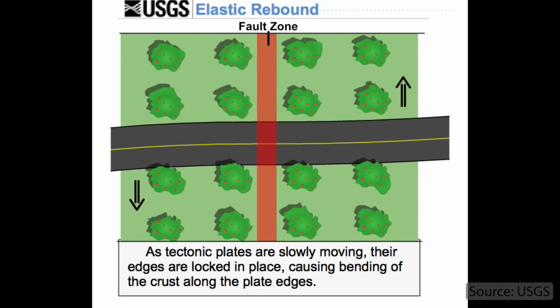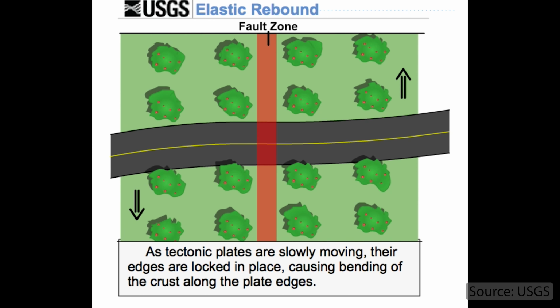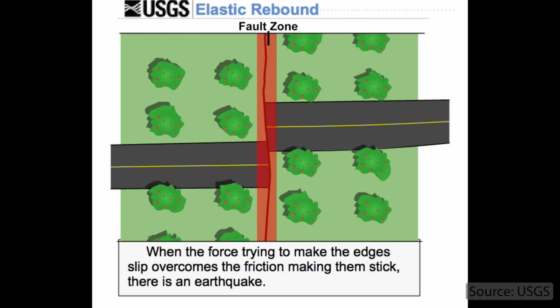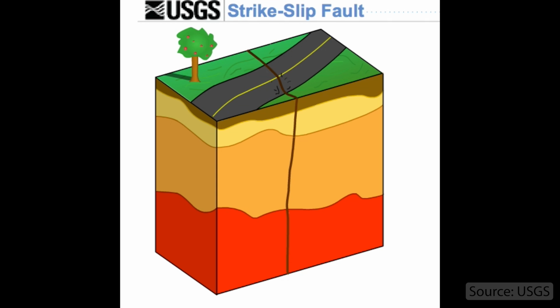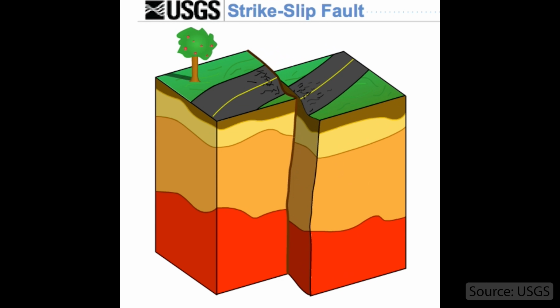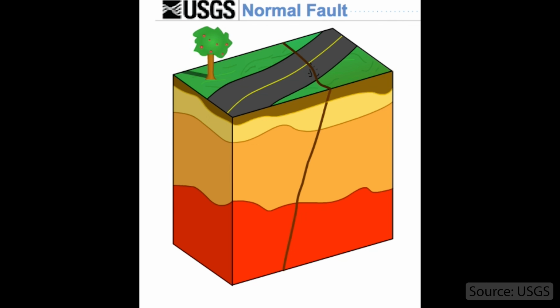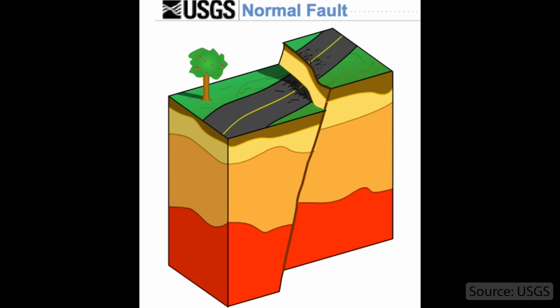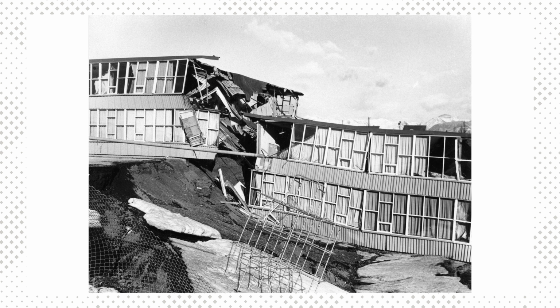A strike-slip fault manifests by predominantly horizontal displacement, as plates slide parallel to each other. This can cause roads to suddenly be misaligned, in addition to generating strong ground motion. In contrast, a normal fault is characterized by a downward drop on one side, creating a vertical displacement. Structures built across faults can sustain damage from both the permanent displacement and intense ground accelerations.